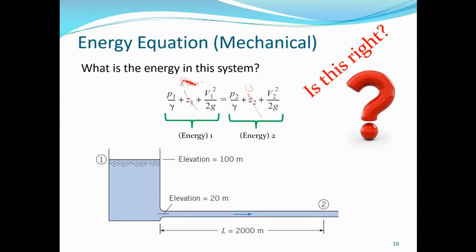Yeah, here, sorry. If we take this to be the elevation, like I explained before, this will be parallel, meaning the total head at point 1 given by this equation is equal to the total head at point 2 given by this equation. The total head remains the same, meaning the sum of the elevation head, pressure head, and velocity head remains constant.